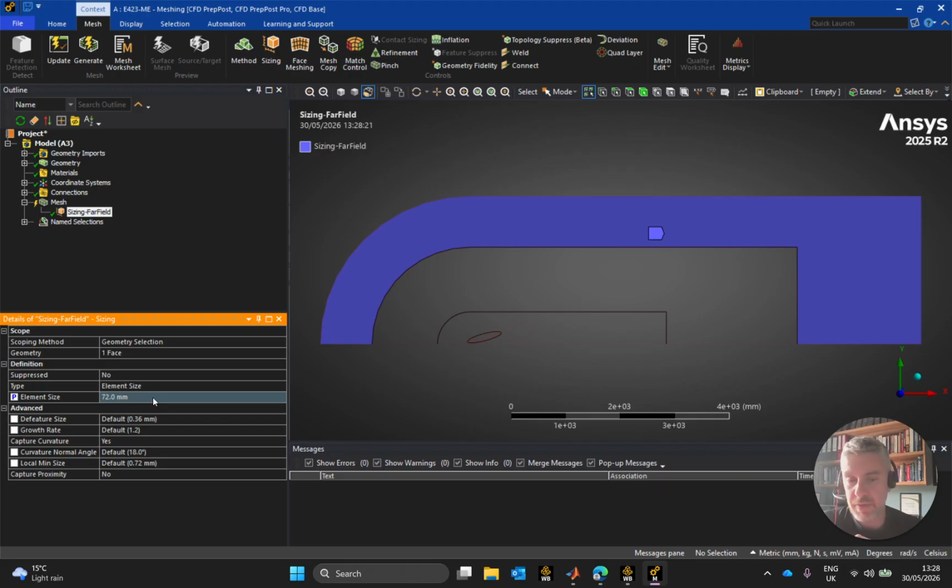The reason for that is not because of grid convergence, grid independence, which obviously is a major requirement in CFD, but because I know I'm going to alter my geometry, and the way I'm going to alter it is going to have skewing effects on the mesh, so I need to keep that very, very fine. So outside the fineness required for mesh independence, I also have a fineness required to allow parametric, parameter-driven sketching, geometry alterations, especially over very small angles. So we'll see how we go with that. Everything else is fine on that.